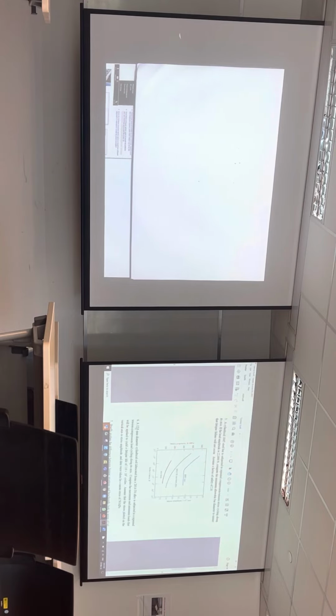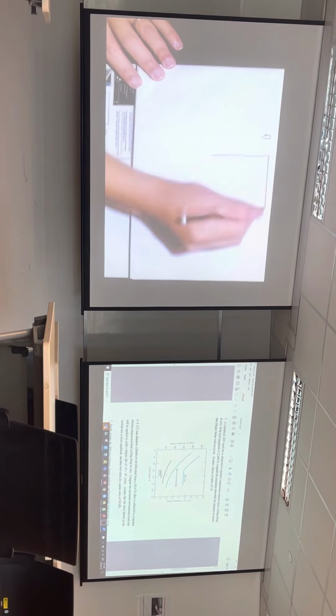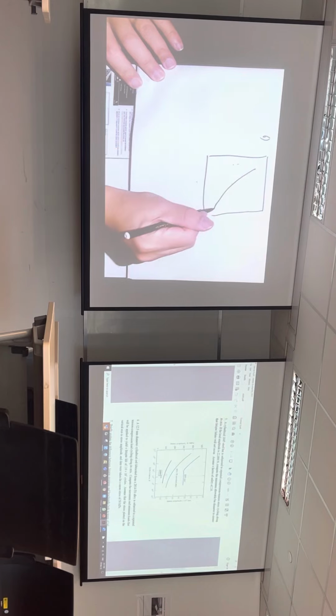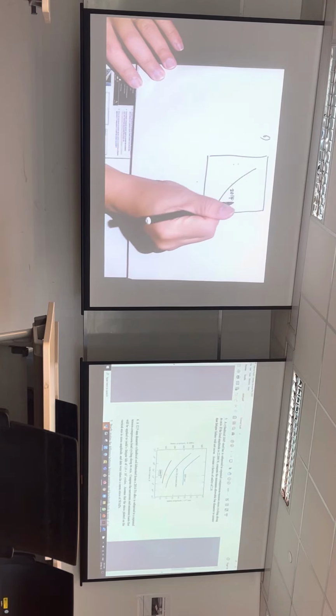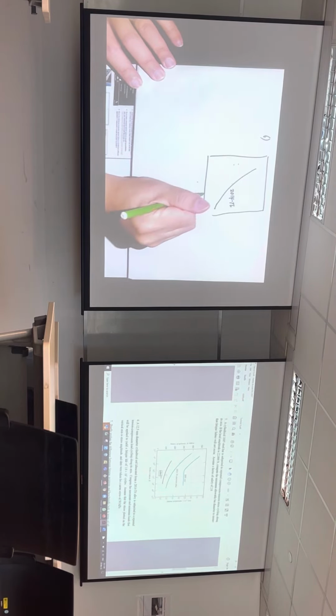So the next question is basically one 12.5 mm diameter cylindrical rod made out of a certain alloy subjected to repeated tension compression along its axis. Compute the maximum and minimum loads that this thing can be applied to yield a particular life of 1.0 times 10 to the power 7 cycles. So you are dealing with this particular green line. So the first thing I can do is question number 6. You're dealing with something over here. So this is your 2014 T6. So over here, you can go up, right? It's 1 times 10 to the power 7 cycles.